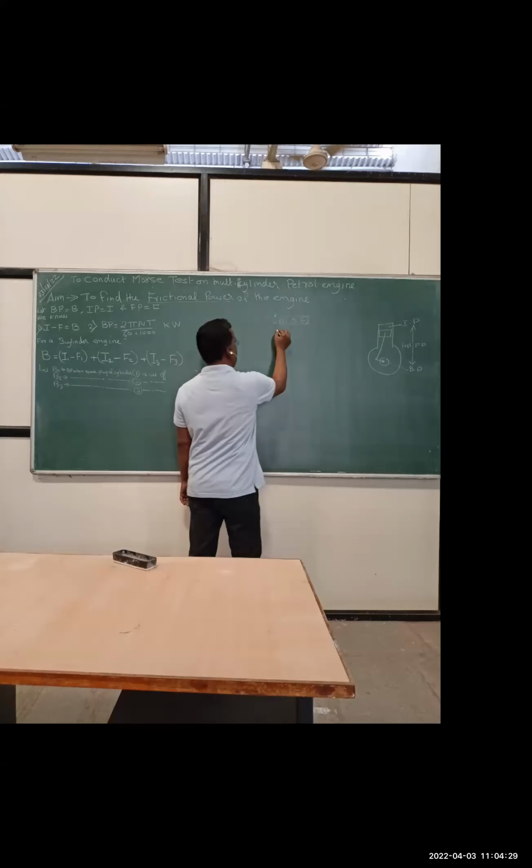That means in the cylinder we switch off, there is no firing. Whatever power is developed will be maximum here, because this power corresponds to all the cylinders firing. While in all these other cases, we have power developed in 3 cylinders, since we have switched off either the first, second, third, or fourth. Right?